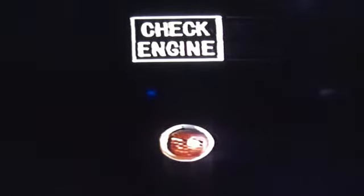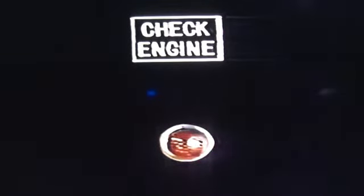Consequently, when you're checking your diagnostics, remember to record all numbers in the memory. Then make any 50 series code repair. Clear the computer memory and do a road test. Finally, check to see if any of the other trouble code numbers you noted are still in the memory. Often the 50 series problem is the cause of the other false codes being stored in the computer.